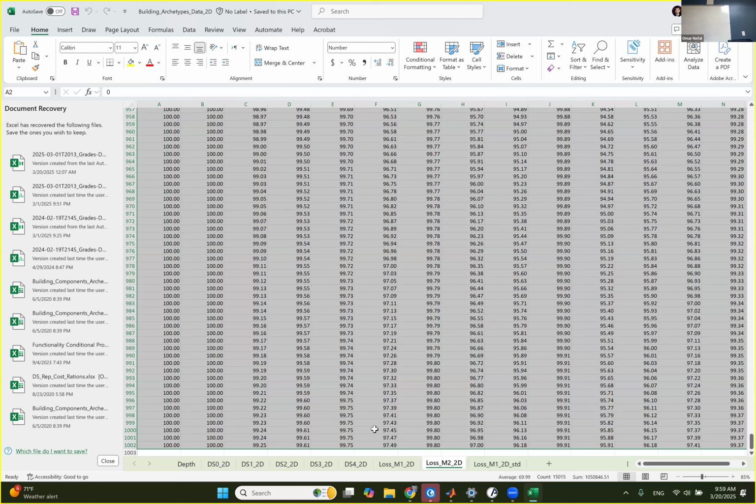Yeah. But I thought about it: the dollar value keeps changing every day or maybe every year. I developed these functions in 2020. Right now, the price is completely different. So at the end, I divided the losses by the total value of the building. Let's say the loss at a specific flood depth was like 10K, and the total building value for this building was like 300K around that time. So what I did, I divided 10K over 300K and I got a percentage.